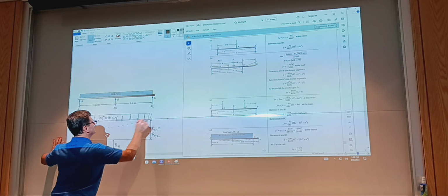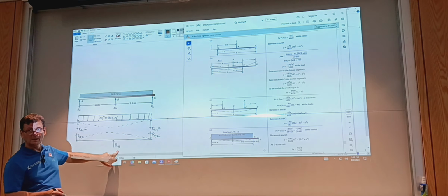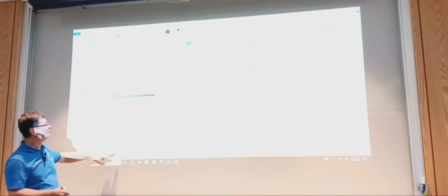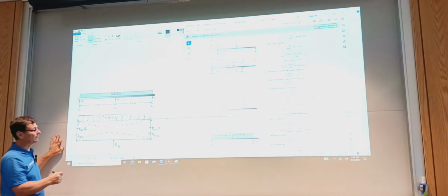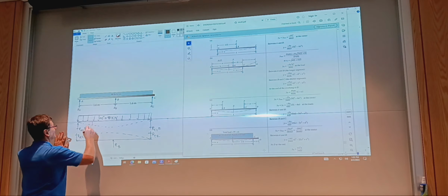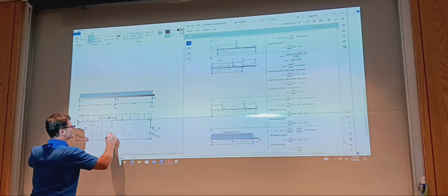Principle of superposition says that I could analyze the problem where I have a simply supported beam with distributed load and a given force acting in the middle, and I can get the resultant deflected shape of the beam by just adding, at a given x, one by one, if I'm to work numerically.